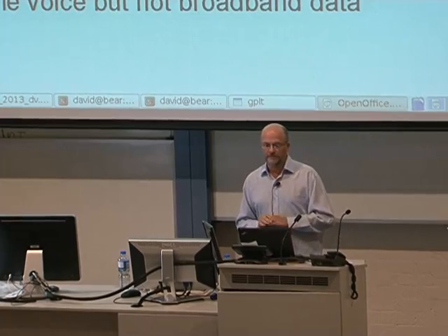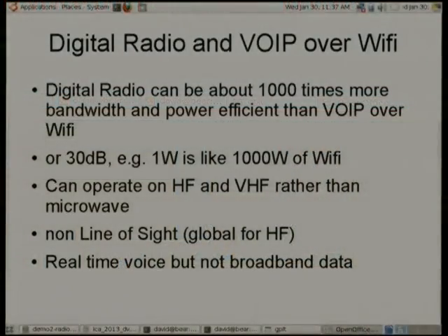So the takeaway from that is that digital radio can be about 1,000 times more bandwidth and power efficient than, say, doing it with VoIP over Wi-Fi. In technical or engineering terms, that's 30 dB. Another way of thinking about that is like 1 watt through a digital radio device is equivalent to 1,000 watts of Wi-Fi in terms of its performance.